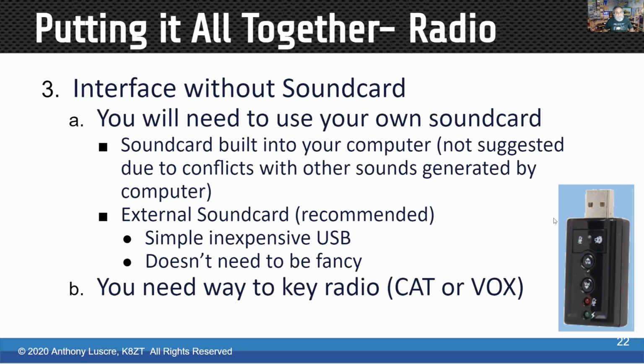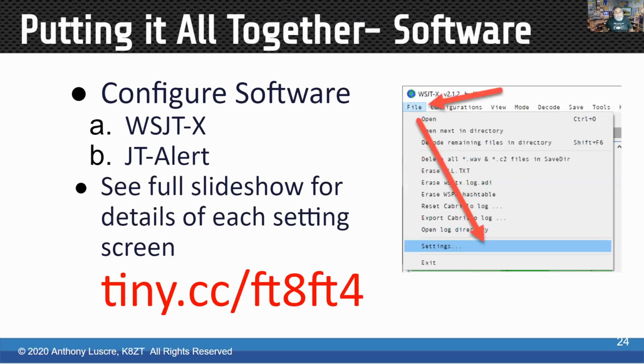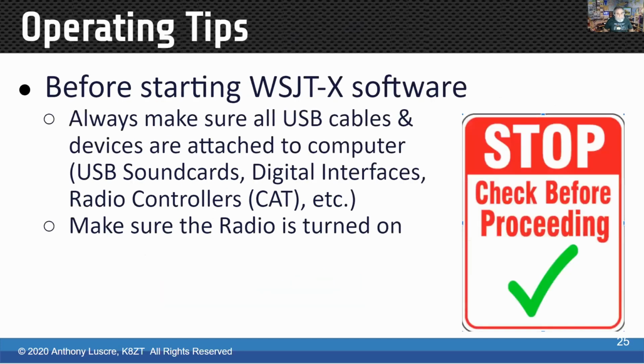What I suggest you don't do is use the sound card built into your computer. There's just too much possibility of messing up between the signals you want to get into the radio from the software and error messages and other noises from YouTube and things you might play with your internal sound card. I mentioned you need time synchronization software if you're running Windows, and there's some settings you need to do in the software, and I'm not going to run through all those tonight.